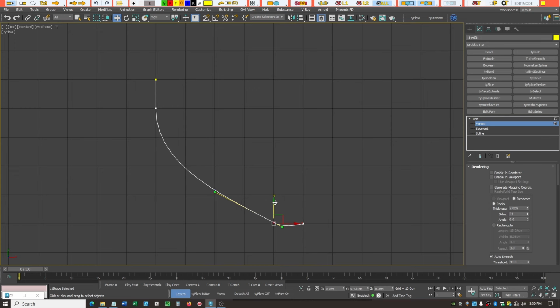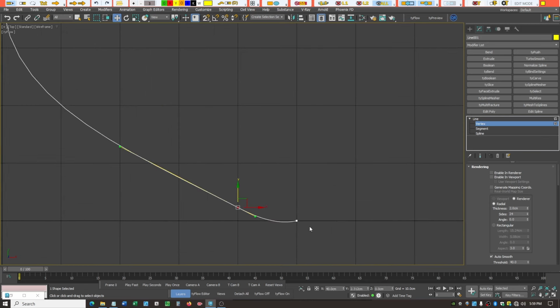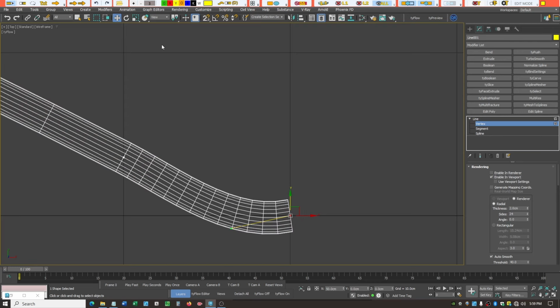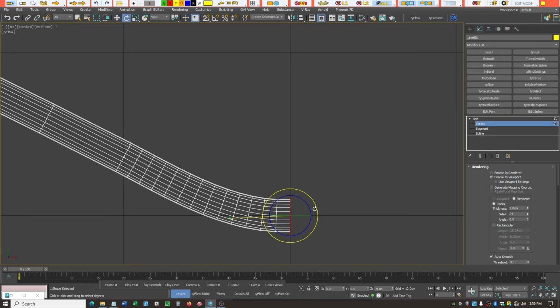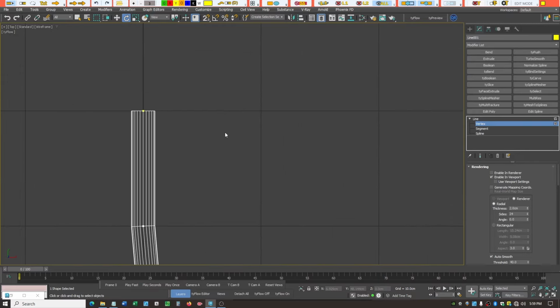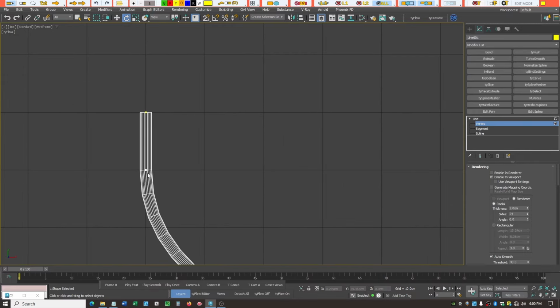So right now, let's tweak that until we get this roughly where it looks like it's going to be horizontal, and you can see it's not going to get there on its own. We turn this on to help visualize, and because we made this a Bezier corner, we can rotate this a little bit until we see that it is perfectly aligned. We need to do the same to the top now. That looks pretty good there.